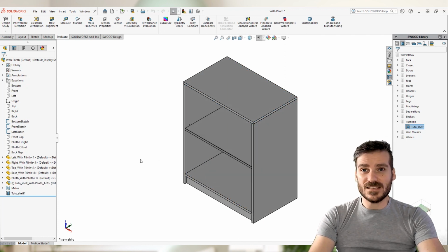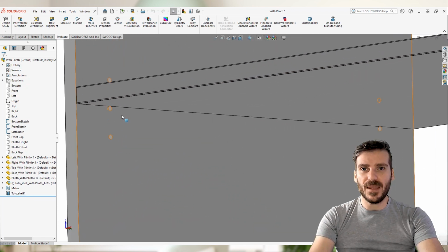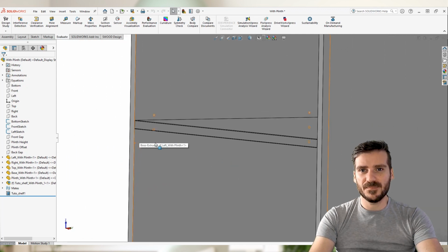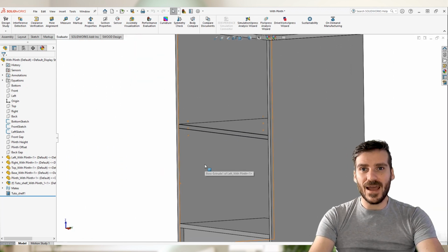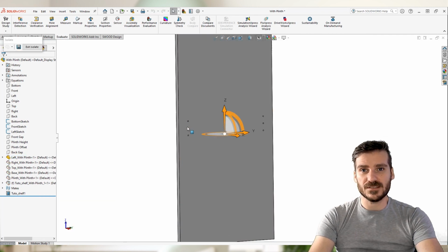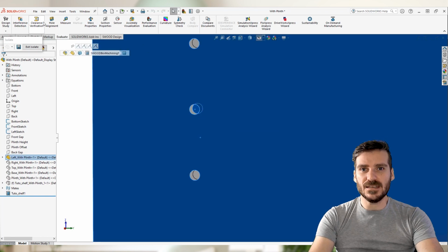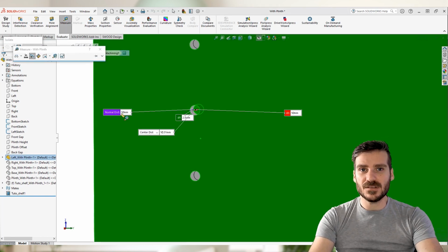Here we can see that our SWOODBox is inserted into the Feature Manager design tree as a new feature. If we look in detail, we can see that the drillings are made on the panel of the frame. For example, if we isolate the left panel, we can see that the holes belong to the part. If we measure the drilling depth, we can see that they are the 10 mm that we have planned.